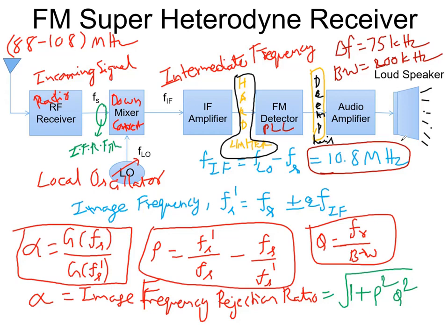Sensitivity depends on the gain of the receiver. The more the number of blocks, the larger the gain, and sensitivity is improved. Selectivity: whenever you are able to maintain a fixed Q, obviously selectivity is going to improve. Then depending upon the reception range of your local oscillator and RF, this is the receiving antenna. Depending upon the synchronization, you are able to achieve fidelity also.